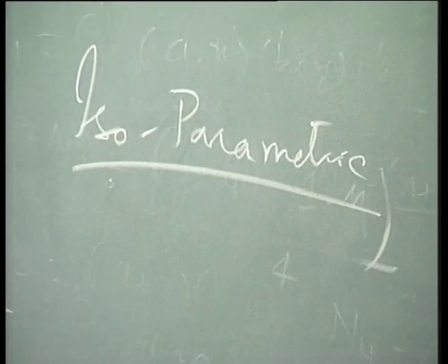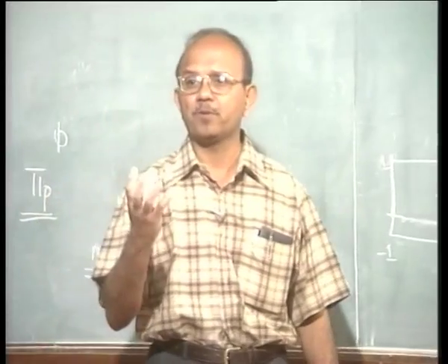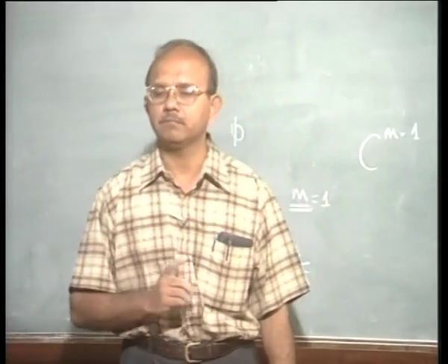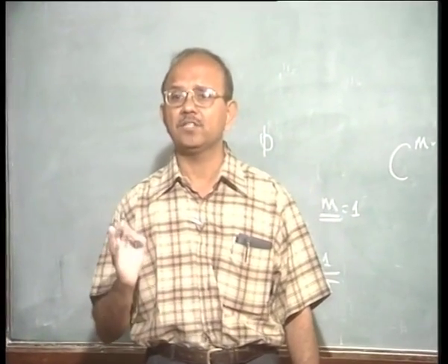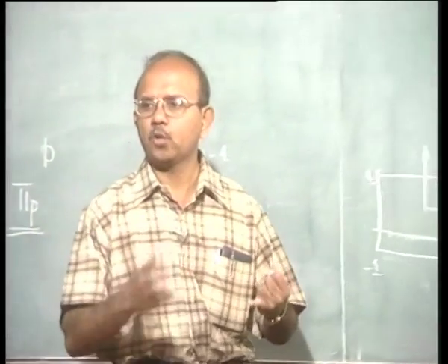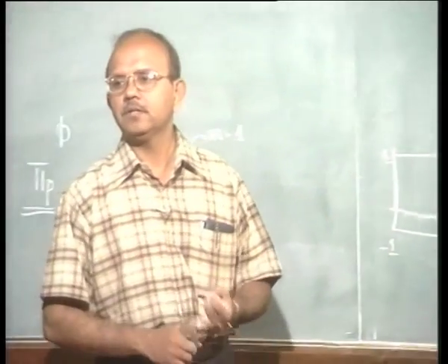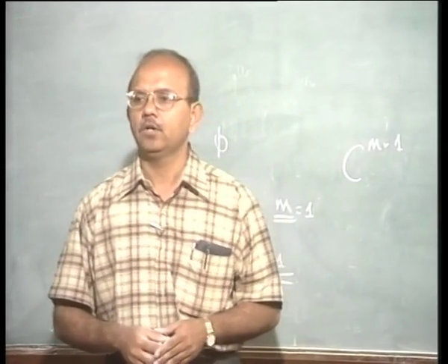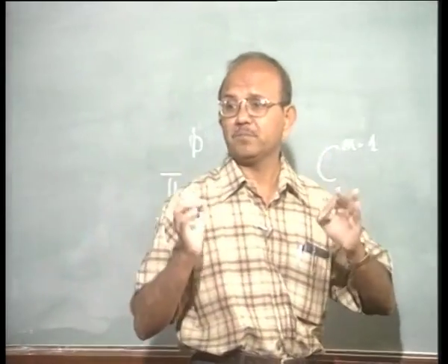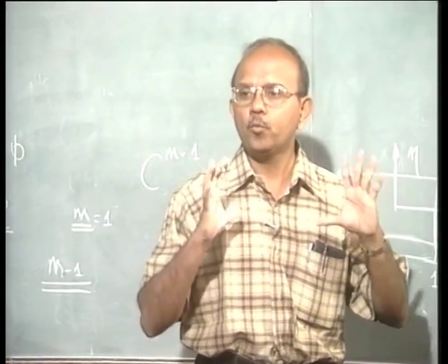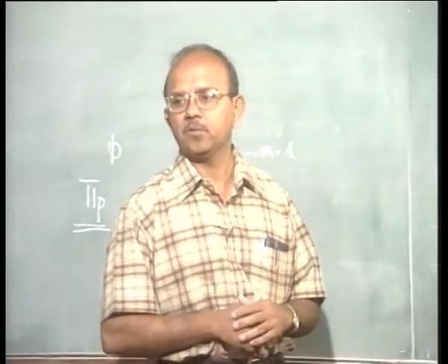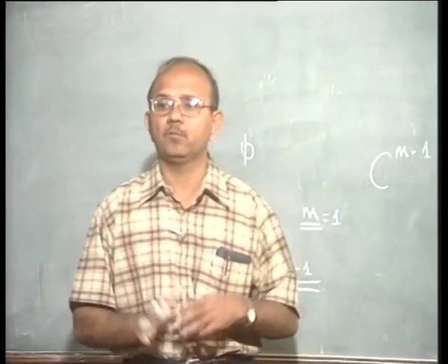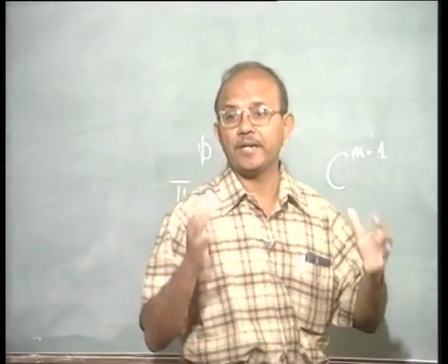Essentially, to appreciate isoparametric elements, you have to appreciate the concept of natural coordinate system. But isoparametric element is a concept which is applicable to brick elements, or in other words solid elements. It is applicable to plane elements, it is applicable to shell and maybe plate. So, isoparametric elements is a generic concept. So, we will study isoparametric elements, and why does this become important? It is the most important concept that has evolved in finite element analysis.